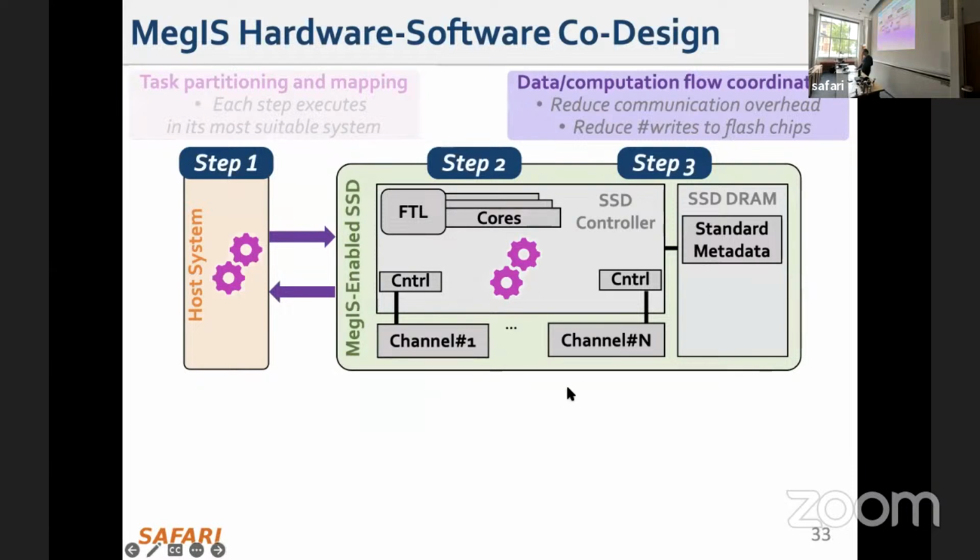One of the issues with the SSD that we will talk about later is that writes are expensive, because when you write to a flash chip, NAND flash memory, you wear out the memory. As you write many times, the memory wears out. At some point, you cannot write reliably, meaning you cannot read the data that you write. This is called the endurance or wear out problem in non-volatile memories. It happens not just in NAND flash memory, but also in phase change memory, for example, and many other non-volatile memories. So clearly, you have limited write cycles or limited endurance.